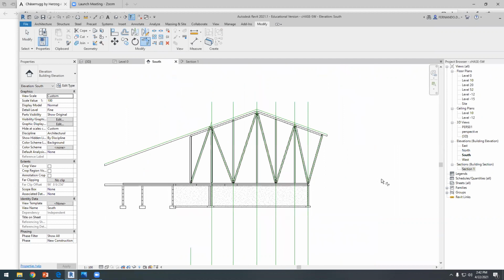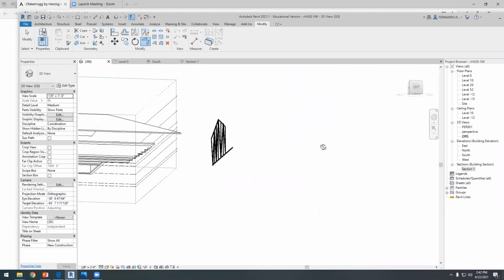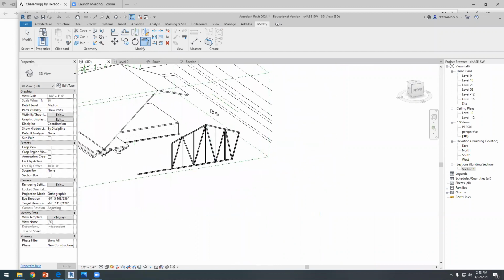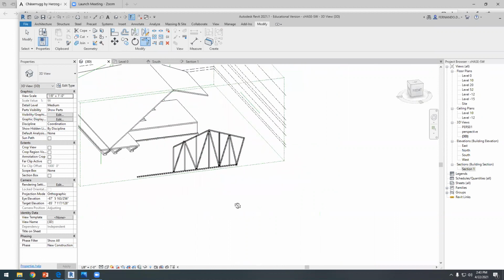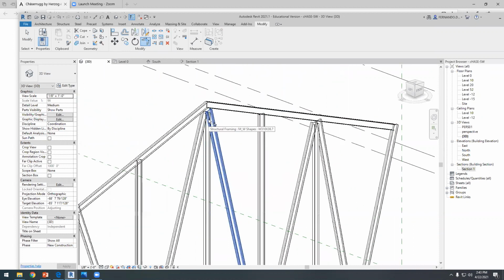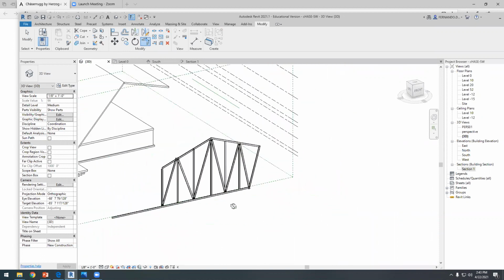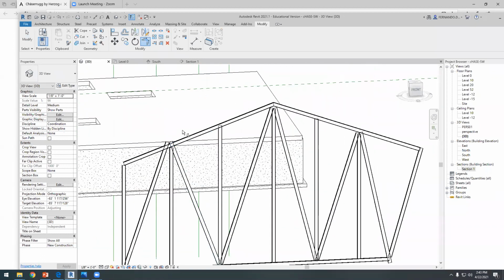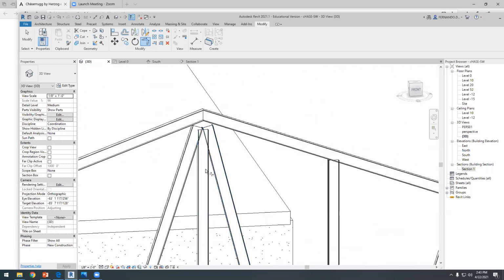Okay, so we have started with a truss that somehow is similar to the one that we want to create, and by not editing the profile, we are just removing the truss family, and then we are working with elements, but they are still connected, there are still points of connection, so we have to move it, and then we have to join all the elements so that we can end up having something like this. Then we can always use our good friend.